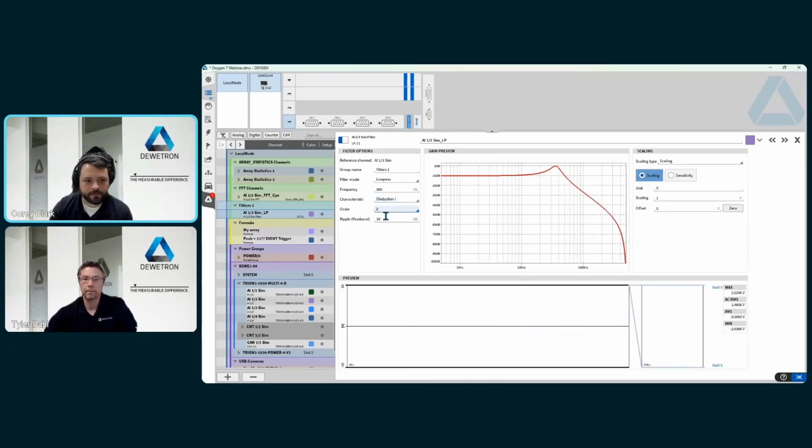So this has interesting characteristics where the lower the order, the less the ripple, but you always have that frequency cutoff ripple here at the elbow, or the knee, and then it comes down. We have a gradual roll off, but as we increase the order, you can see the rippling increases across the passband, and we get a steeper roll off after the frequency cutoff point. And that would be our Chebychev 1 and 2 filters.